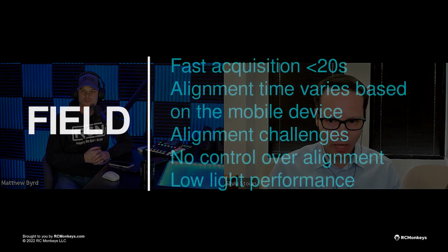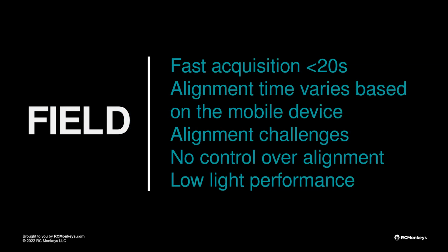Just to give it a hint, right? They're like, hey, we're working in this area right now. We're not at the other end of the building, right? And the other thing is the low light performance. So on the project that I just showed you, we scanned in the crawl space, which was pitch black, and then the attic. In order to prepare for those conditions, we used an LED rig that we clamped to the tripod, and some additional LED panels that we scattered around to get some good lighting. So we didn't have any issues scanning those spaces.